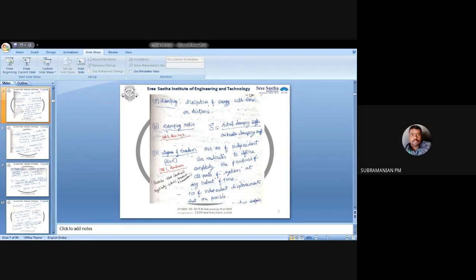And forced vibration, we have seen some examples. Then vibration control, that is what we have to do to avoid vibration. So what you have to do is avoid resonance. That is, you have to ensure that my excitation frequency should not match with my natural frequency. And I have to increase the level of damping, and I have to reduce the magnitude of excitation. That is, what is the unbalanced force that is going to come now. That unbalanced force magnitude I have to reduce.